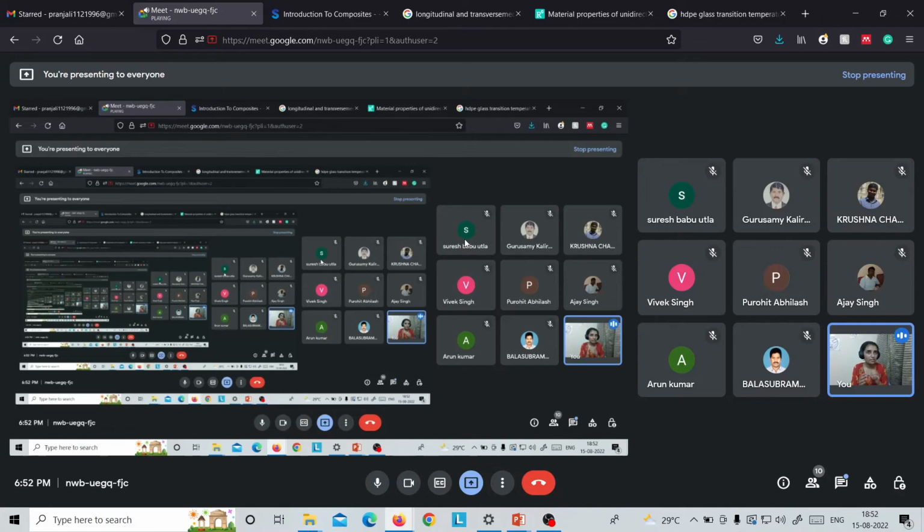That particular structure will not directly start breaking down. First, the temporary bonds holding that structure together will start degrading. Once the temperature is beyond that particular energy level, the actual crystalline structure will start degrading. So that's where semi-crystalline will also have two stages: one in which the temporary bonds which hold the crystalline structure together will break, and the second in which the entire crystalline structure will start breaking.